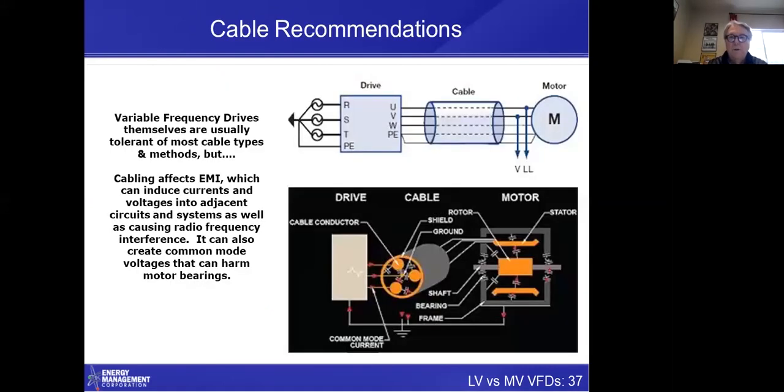Now, on low voltage drives, more and more motor manufacturers and drive manufacturers and motor repair shops like EASA, the Electrical Apparatus Service Association, recommend that anytime you have a VFD, you use special VFD cable to go between the VFD and the motor.